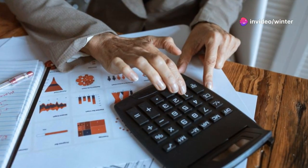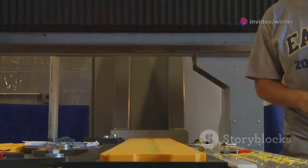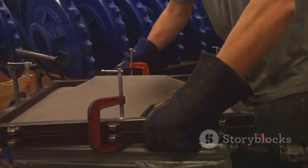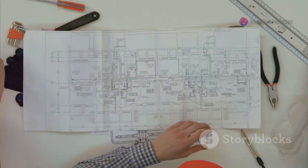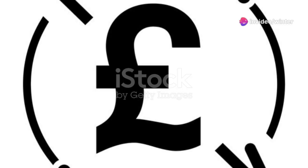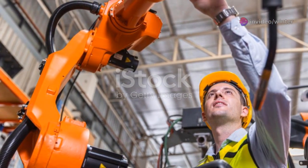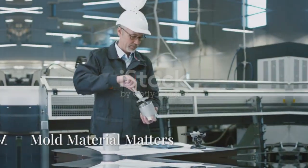Do the math. Calculate your break-even point. For cheap materials and small runs, cold runners win. For expensive plastics and big volumes, hot runners are the way to go. Match the runner system to your project's needs. Don't overspend on features you don't need. Make the right call for your production scale. That's smart engineering.